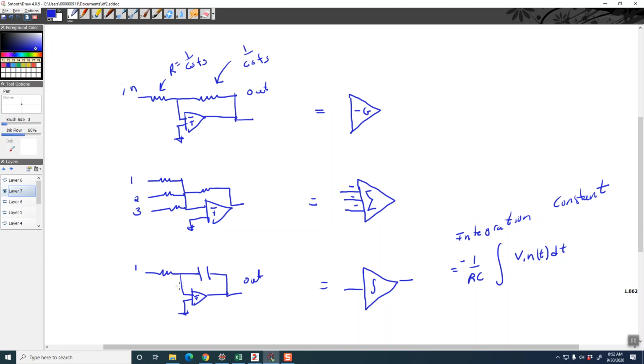And here we have an integrating inverter, an inverting integrator, excuse me, which you can use the integrating symbol, or sometimes we like to use 1 over S. Now, yes, the equation's really minus 1 over RC. That would be the feedback, and this R would be the one that's programmable. And so rather than using these actual circuit parameters when you're doing a circuit, you can use kind of like signal flow blocks.